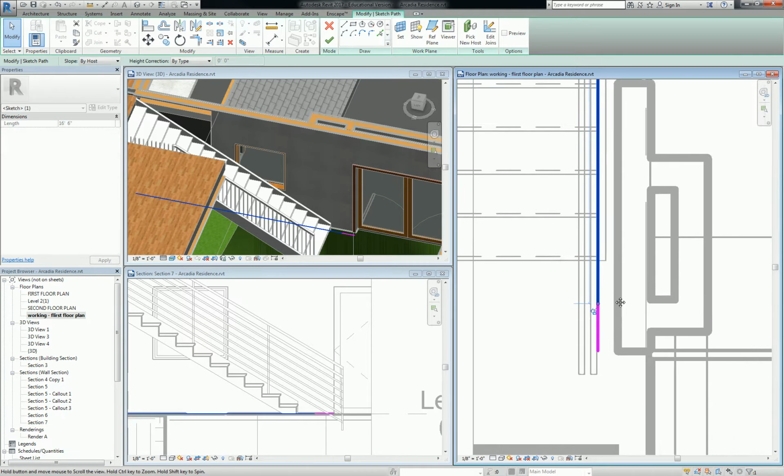There we go. So the second floor, this railing, let's go to guardrail pipe. When you're doing something like the second floor element, notice how this thing actually comes up and then runs and then turns and then runs and then goes up again. Unfortunately, in Revit, you sort of have to do that. And in commercial projects, there are some code requirements that sort of elongate that extension a little bit. In a residential project, you can get around some of that. But basically, we have to edit this path again.